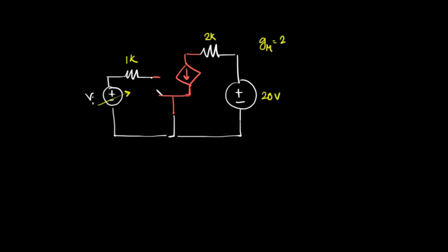So if I put a voltage of 1 volt at the input, first of all, will any current flow in the input loop? Will any current flow here? Well, no current will flow here, because as you can see, this is an open circuit. There is no connection in this place, so no current can flow. But we don't need any current to flow in a FET, because a FET is not current controlled, it is voltage controlled.